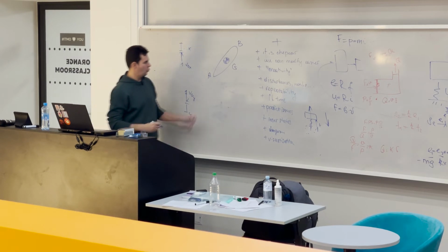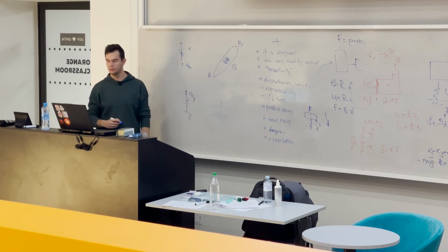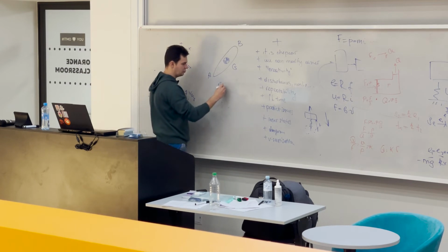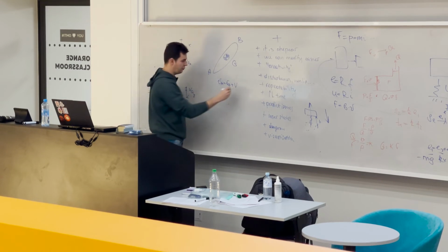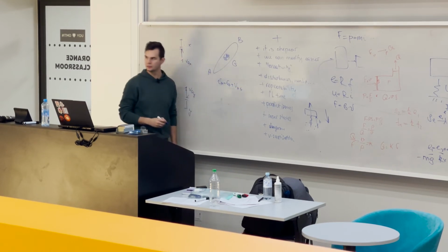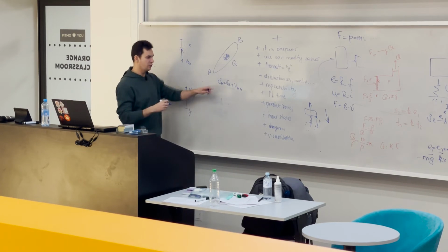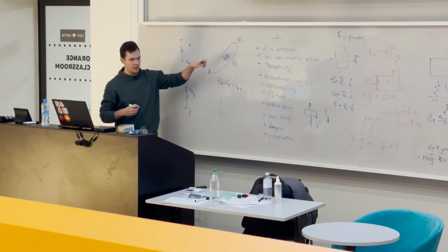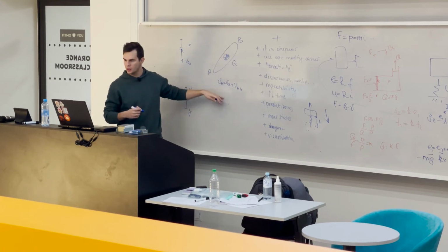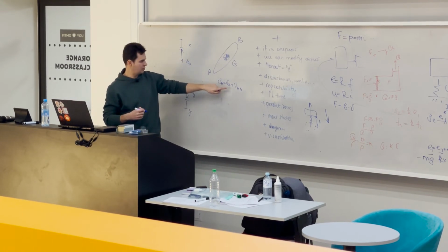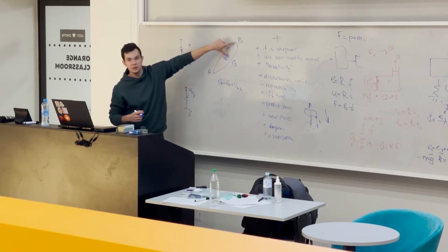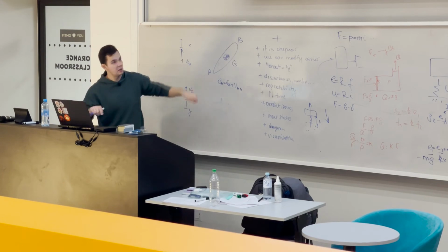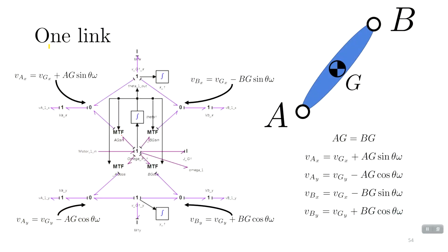All right. What will be the velocity of point A? Velocity of point A equals the velocity of point J plus the relative velocity of point A around J. The same is true for B. And if we derive an equation for the x and y, here will be Jx, and here will be sine theta times this lever. So actually it will be those equations. Okay?